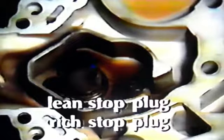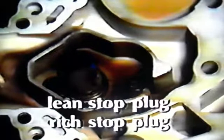Before setting the air horn aside, there are two more plugs that need to be removed. They are the lean stop plug and the rich stop plug, which you'll want to save and replace in the carb later. To remove the lean stop plug, you have to take the punch and tap it out. This will give you easy access to the lean stop adjustment screw later on.